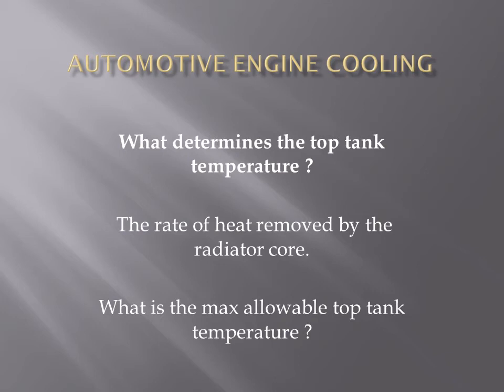Now, throughout this whole presentation, there are two very important statements. Statement number 1 said that the temperature difference between the inlet and outlet temperature of the radiator is only determined by the flow rate of the coolant. And this statement here is the other important one. The top tank temperature is only determined by the rate of heat removed by the radiator core versus that of the engine.